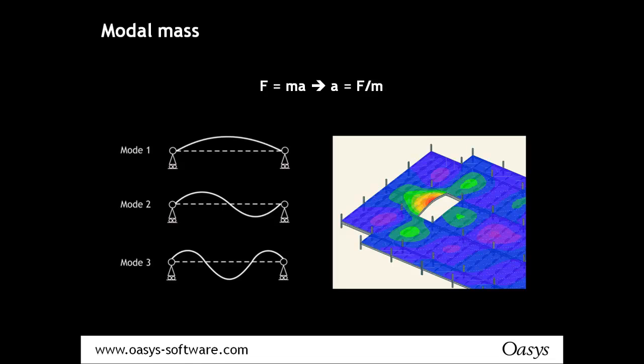That example there on the screen, that's an irregular or an isolated bay, which means it doesn't really grab much of the surrounding floor, which means the modal mass of that particular mode will be relatively low, and so you tend to get some quite high responses on these irregular or isolated bays.